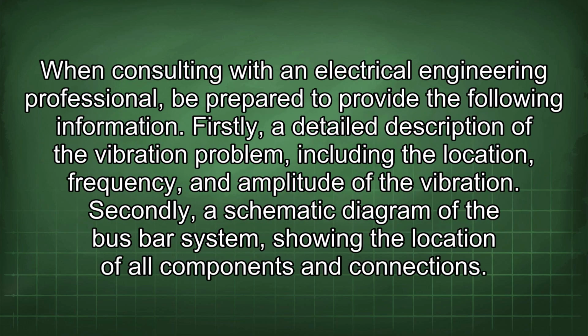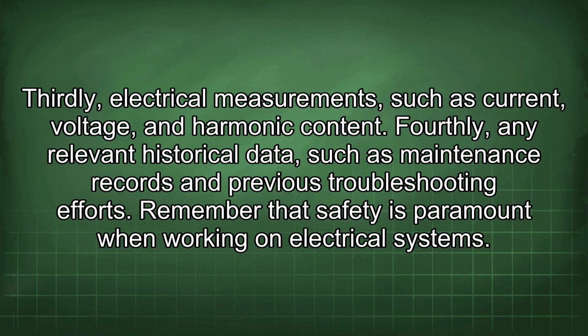When consulting with an electrical engineering professional, be prepared to provide the following information. Firstly, a detailed description of the vibration problem, including the location, frequency, and amplitude of the vibration. Secondly, a schematic diagram of the busbar system showing the location of all components and connections. Thirdly, electrical measurements such as current, voltage, and harmonic content. Fourthly, any relevant historical data such as maintenance records and previous troubleshooting efforts.